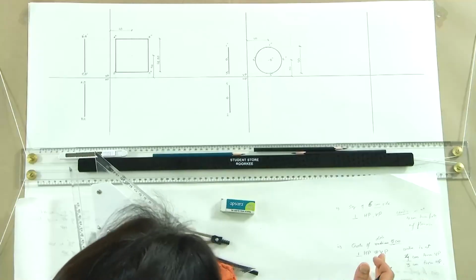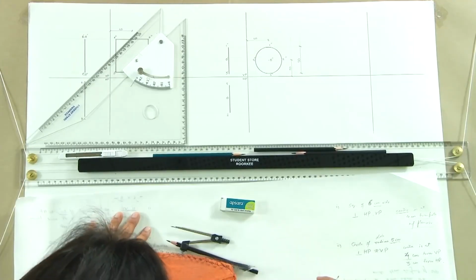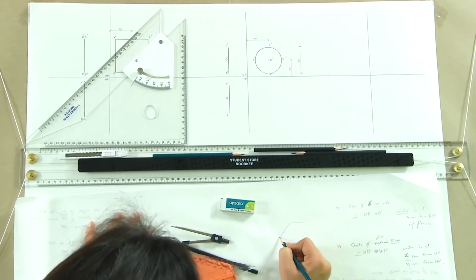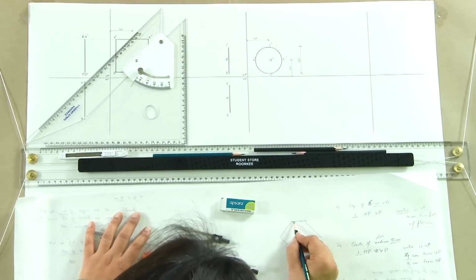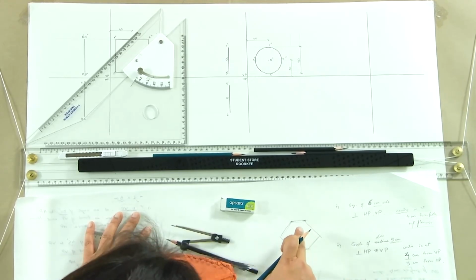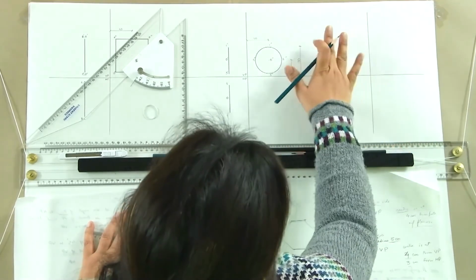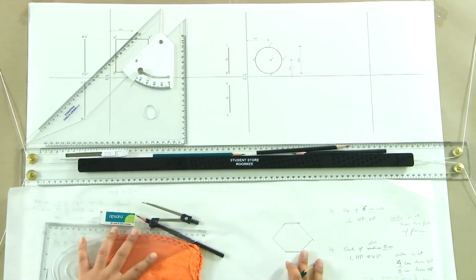Similarly, you could be drawing anything. Try drawing a hexagon which is perpendicular to both the reference planes and its 2 sides. So, when we are drawing a hexagon, 2 of its sides are parallel to HP. So, when you draw the hexagon, it will be lying like this in the side plane, because two of its sides are parallel to HP. So, you can start by drawing a hexagon in the side plane, and then you can have its projections drawn onto this. Just to give you, this is what you have to try at home.